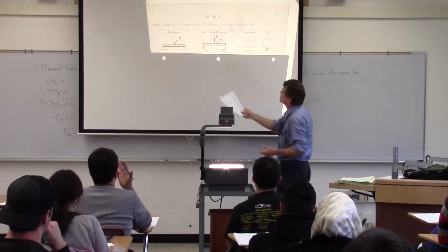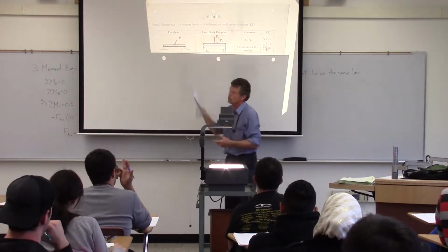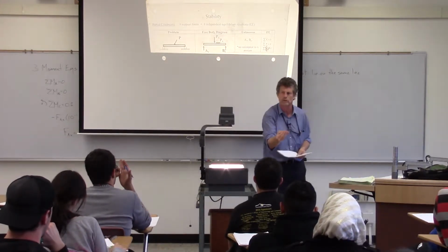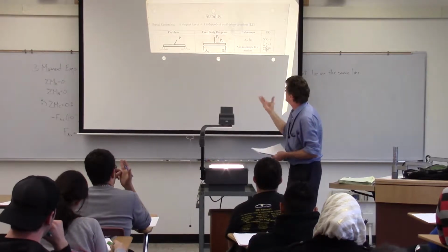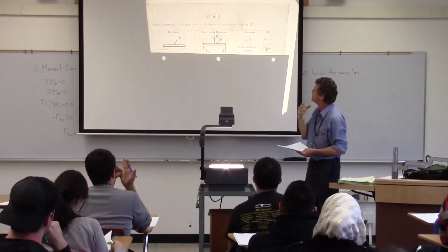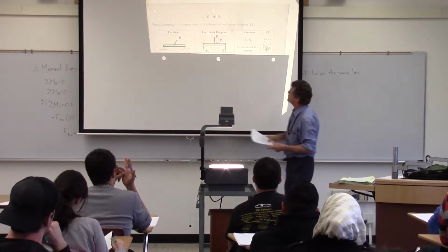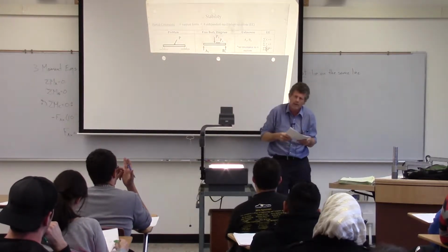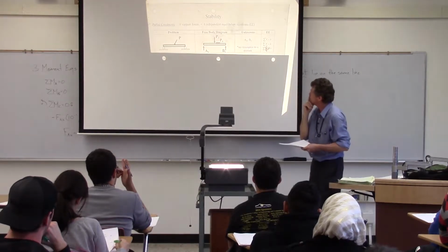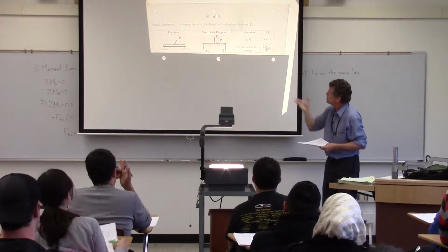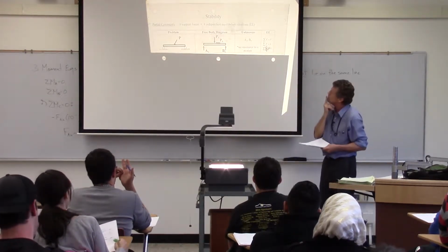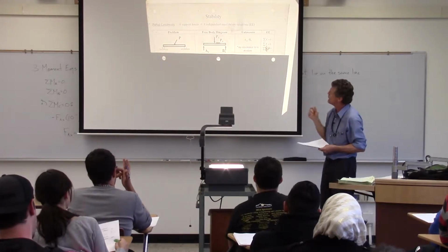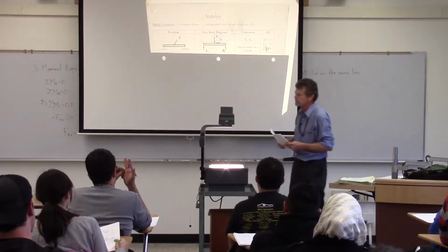So this is a situation where it's considered a partial constraint, where basically the number of support forces is less than the independent equations of equilibrium. Now, we could solve for that if P was absolutely vertical there, then we can solve for it. It's partial, but again, we can go in and start solving for some pieces. But in this particular case, stability, we wouldn't want to put a building on that or something like that, unless it was in an earthquake zone or something.